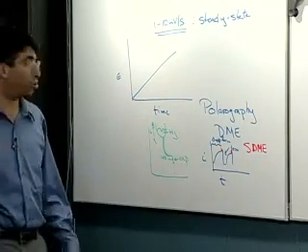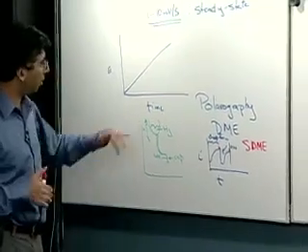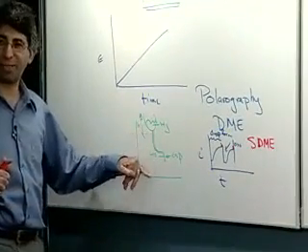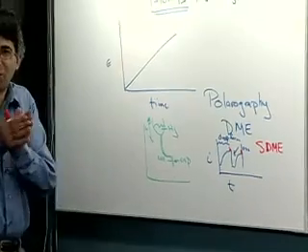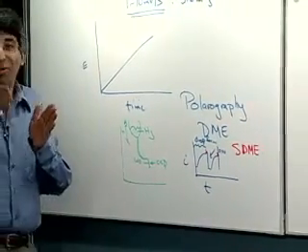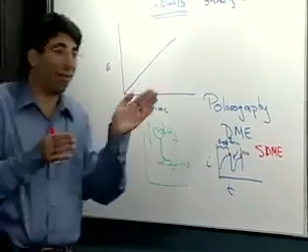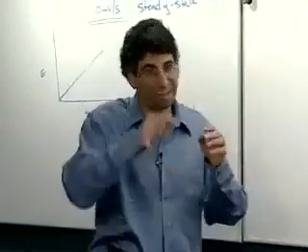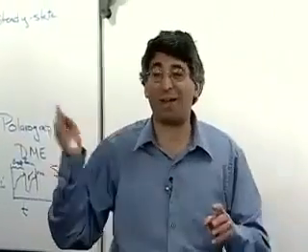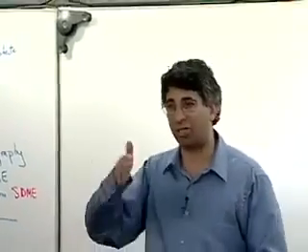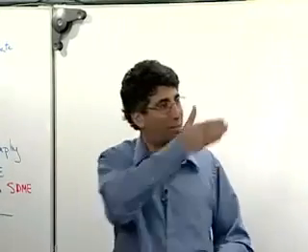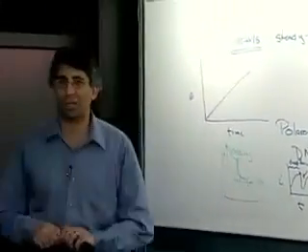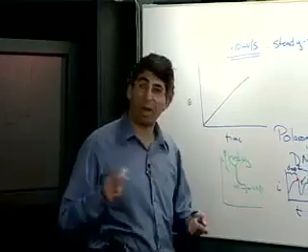But how are you going to do that if you're using just the natural drop frequency here? That is, your electronics don't know when to sample, because they don't know when the drop is going to fall off. And there are subtle things in that, like exact heights and whatnot, and whether there's any vibrations in the building, things like that, that will change the natural drop rates. It's not exactly a perfect reproducible phenomenon. And so what you want to add to your system, which was done, I believe, around in the 60s, maybe even in the early 70s, is a drop knocker.